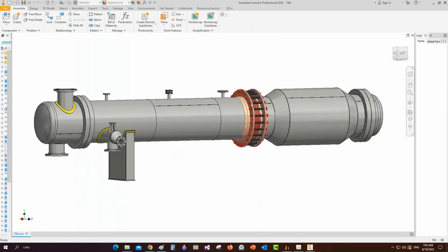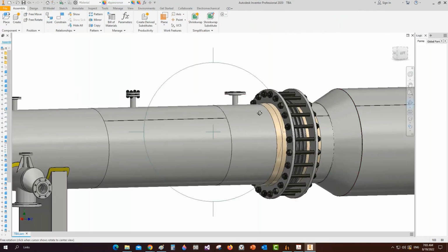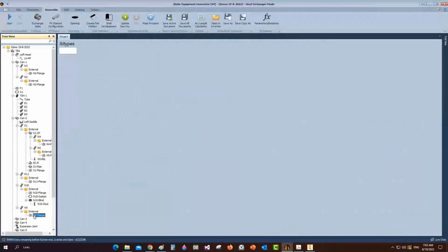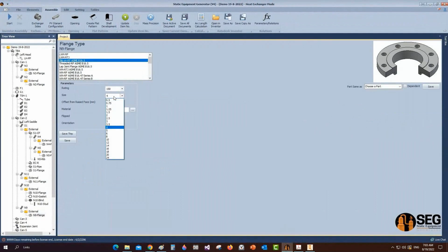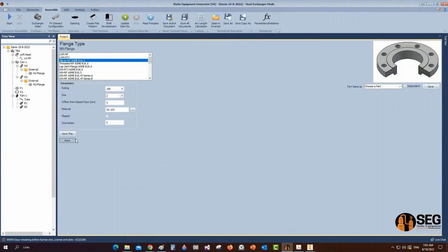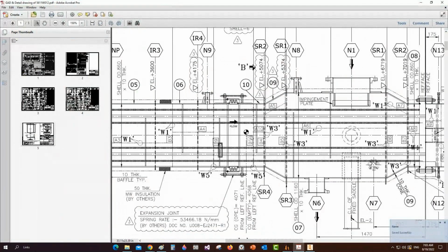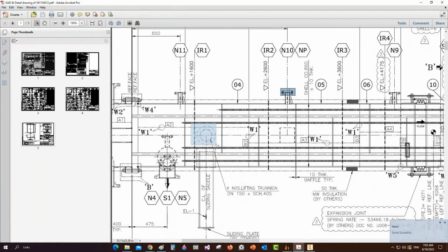Okay, the flange size, I think we select the wrong size, so let's come back here, and from N9 let's select 2 inches, okay, and 5 millimeters. Okay, now let's add another elements. Here we have on the same part we have a trunnion and some of stiffening rings. We have a stiffening ring here, there, there. So let's add this trunnion first.